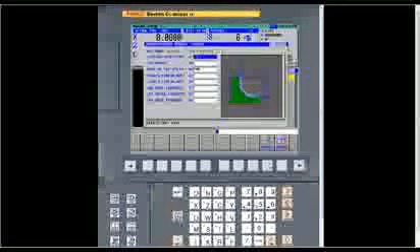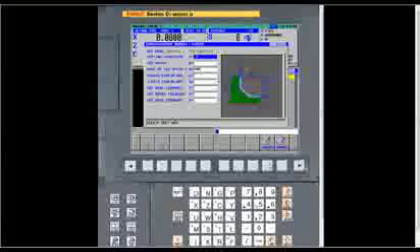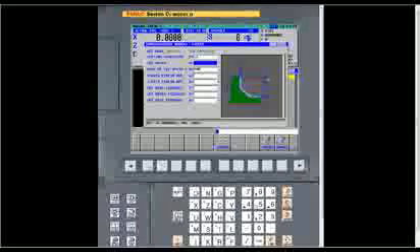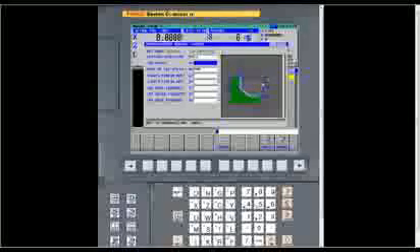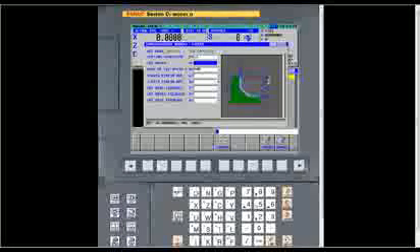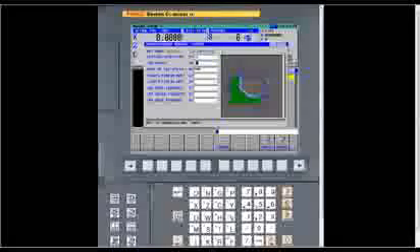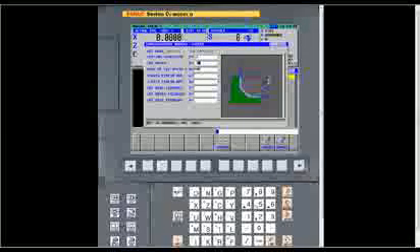We'll select outer rough. And again, it's just fill in the blanks, just like the drilling cycle. Whenever you put information into it, like here, we'll just go Z, Z minus, then it's asking for a cut depth. And you can see it highlights Q, so that it's the depth of cut per side. This is a radial amount. It's very important that you remember that.